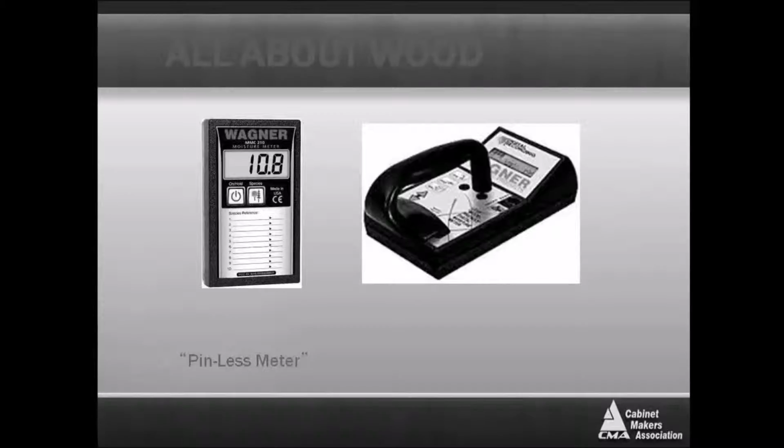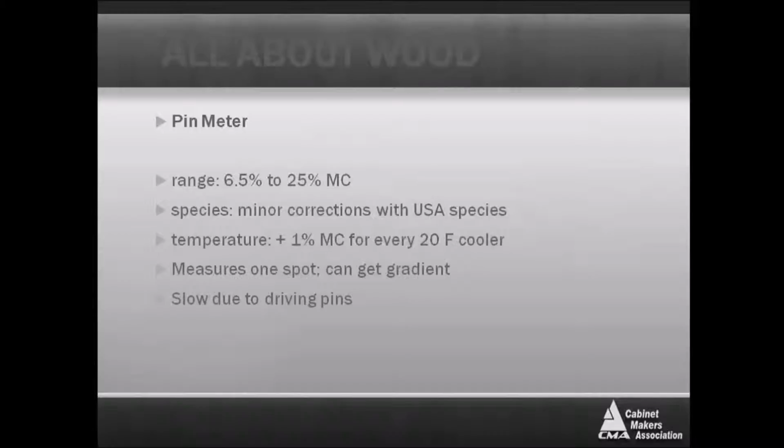Many of you are familiar with that pin meter. We also have a pinless meter. The pinless meter doesn't have pins, but it measures the dielectric property of the wood. The dielectric property then is related to moisture content.